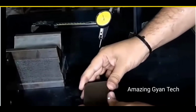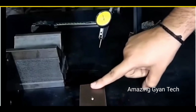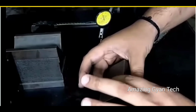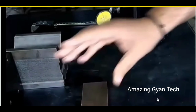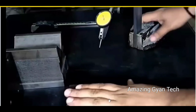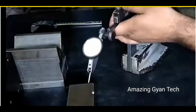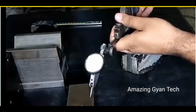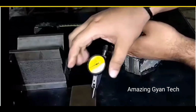So here you can see this is the component which they are going to check for parallelism. One face they are going to check with respect to the bottom face. So the bottom face needs to be rested, and the other face they will be checking for the deviation using a dial gauge. It is clearly rested on the surface plate, and this dial gauge will be applied on the opposite face, and some pressure is applied, and they set the dial gauge to 0, and it will be moved all over the surface and checked for the deflection in your dial gauge.